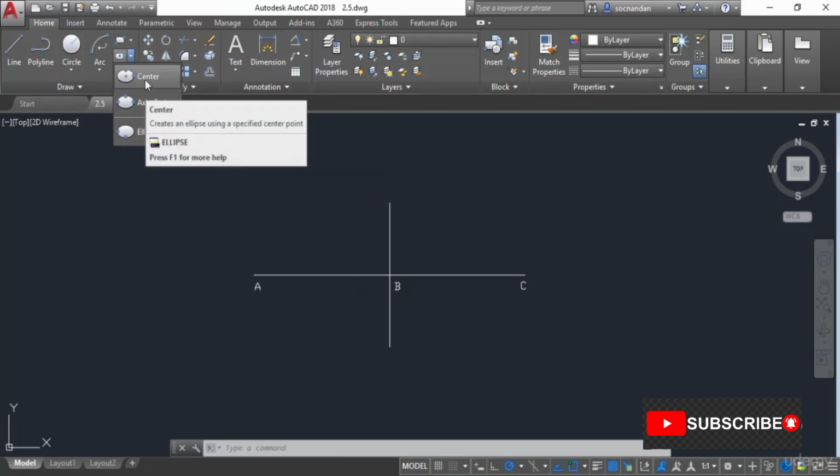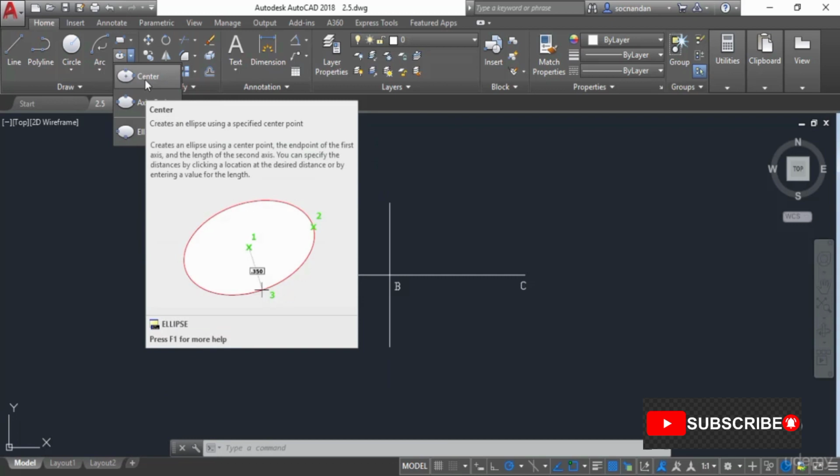So I'll start with a simple ellipse. Now as you can see that in this ellipse we need to enter 3 different points. So for making this ellipse we need to start with the center point. That will be the first point as mentioned in this flyout here, and then we need to enter the second point, that will be the end point of one of the axes, and then the third point which will be the end point of another axis.